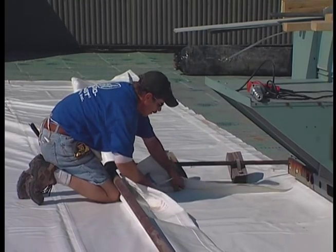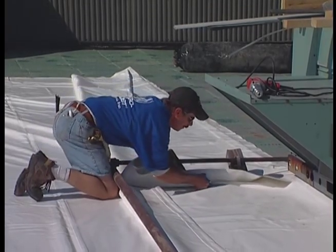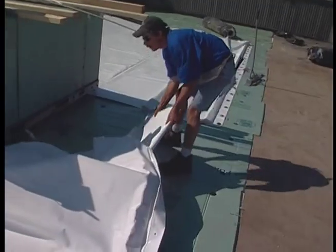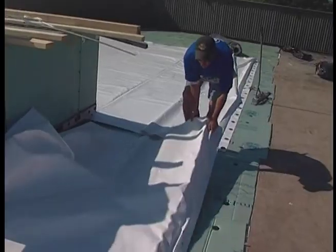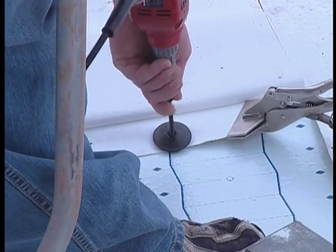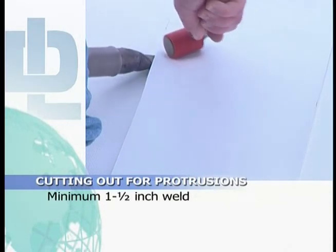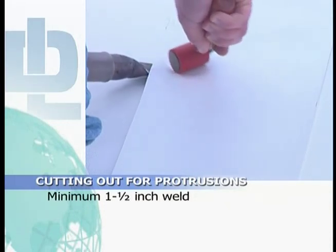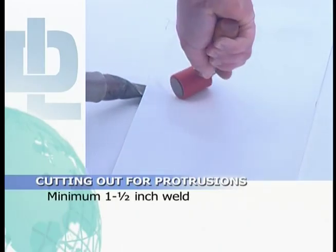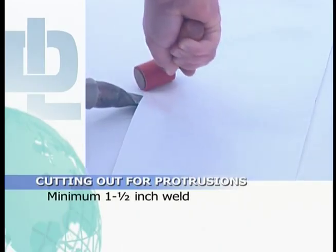If the protrusion is too tall to work through the membrane, a cut must be made to the nearest edge of the sheet. Cut out for the protrusion and fold the material around the protrusion. Fasten the next fastening tab and then weld a strip of Duro-Last membrane over the cut. The strip must be wide enough to assure a 1.5-inch weld on each side of the cut.